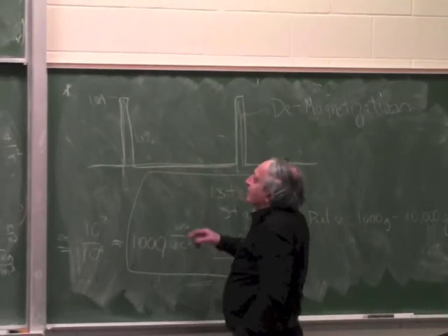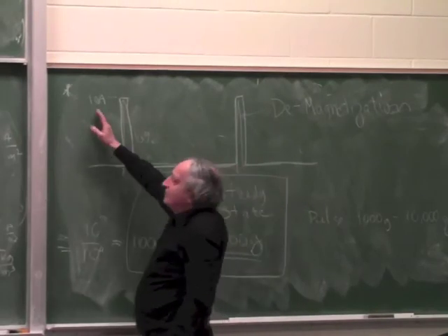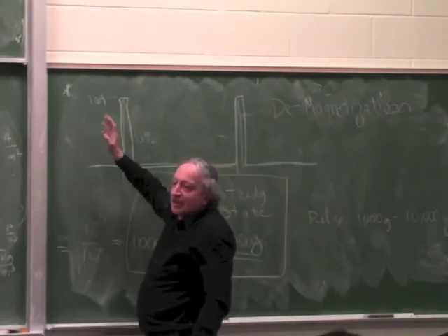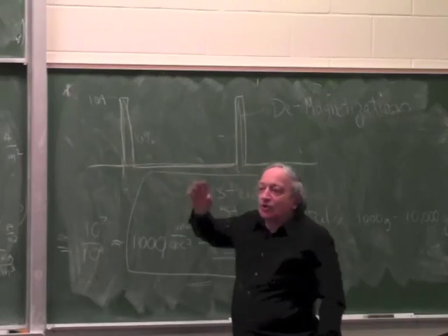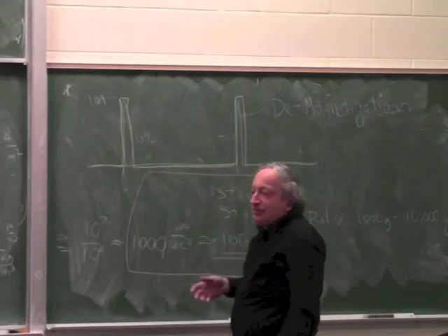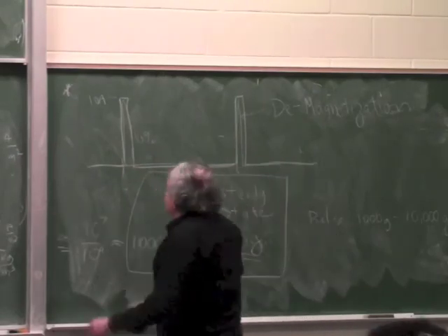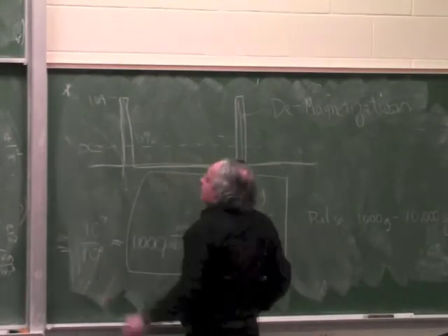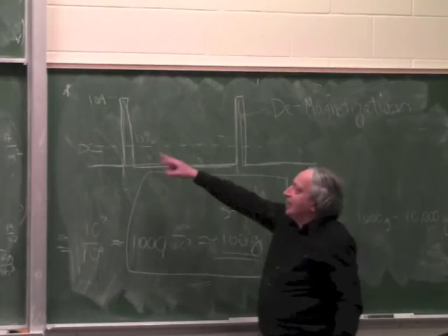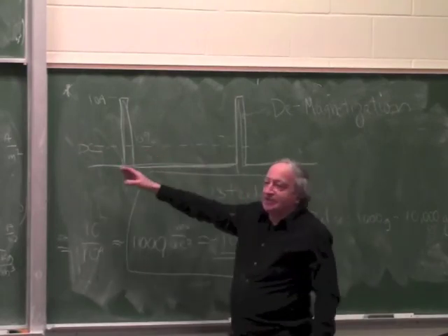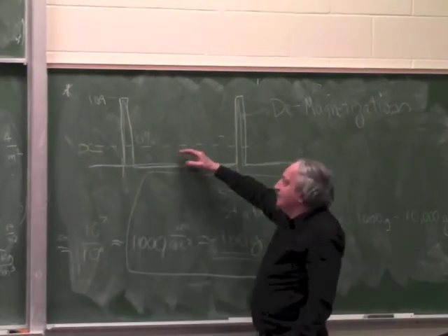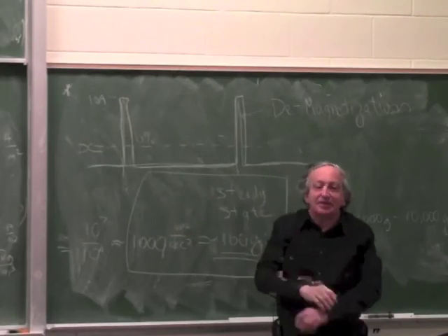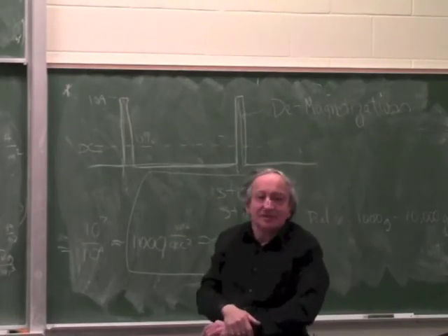During this 1 second, for a tenth of a second, you have 10 amp. And I want to calculate to what DC current this is equivalent, because the heating is derived by an equivalent DC current. So if I want to convert this 10 amp for 10% of the time to DC current, what would be the DC current which will replace it in terms of heating?